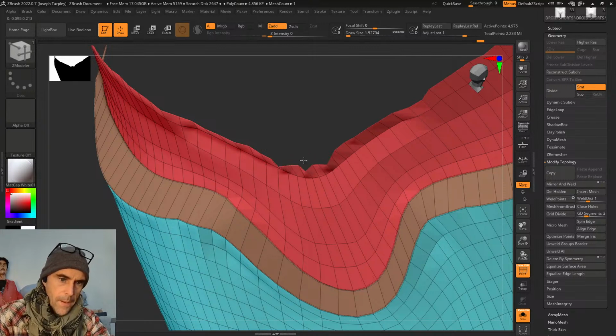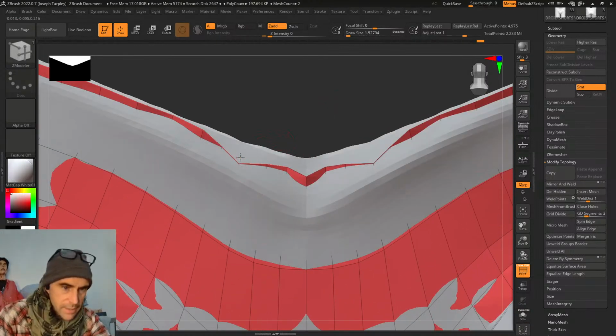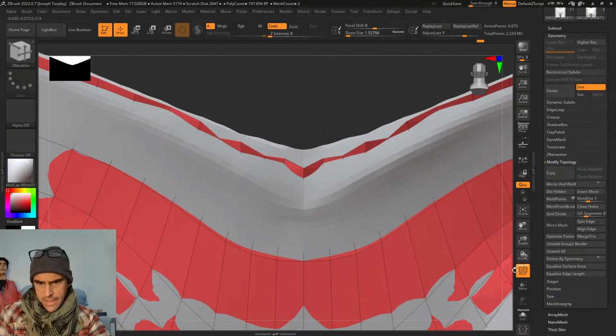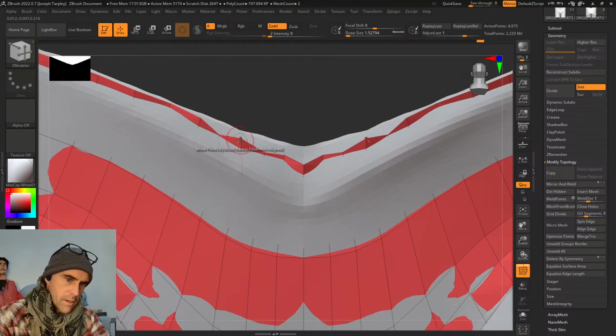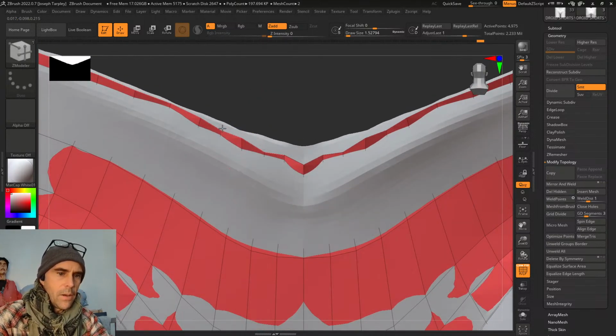And again, I'm just sort of generically pulling them away from the surface, and I'll turn the other layer back on so I can see it. Now, you see when I move it, how the other one disappears? That is because I accidentally put dynamic right here on solo. Turn that off, and then everything stays on. And I could not find that when I started doing ZBrush.